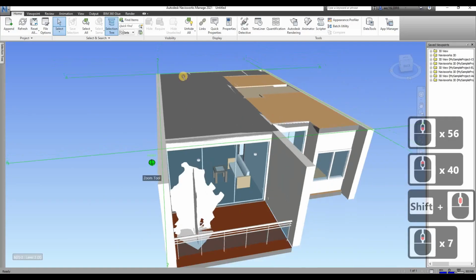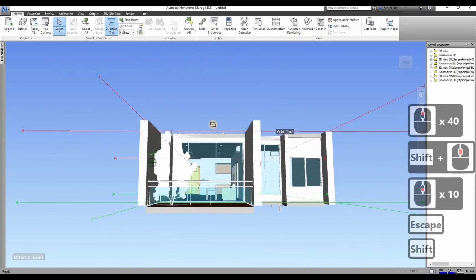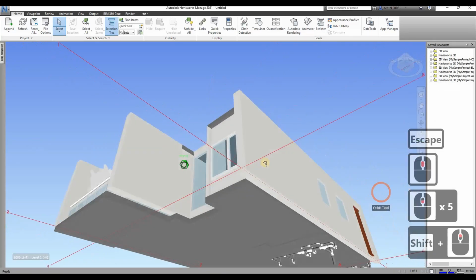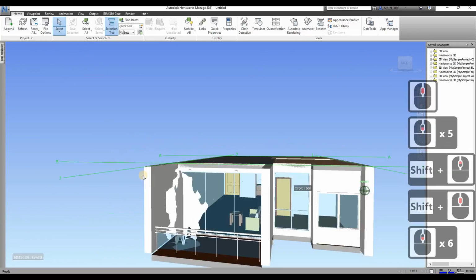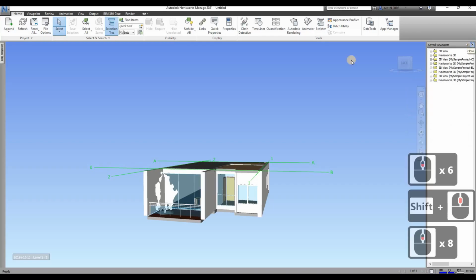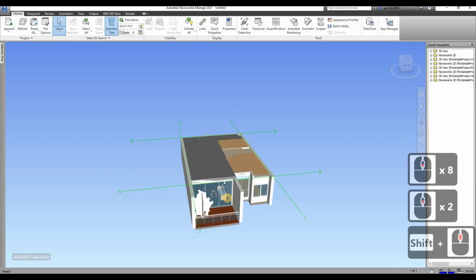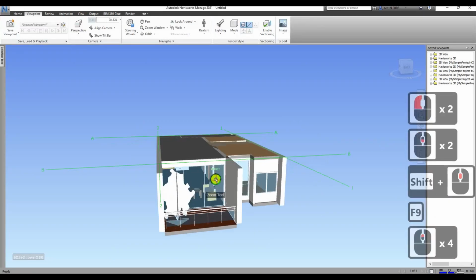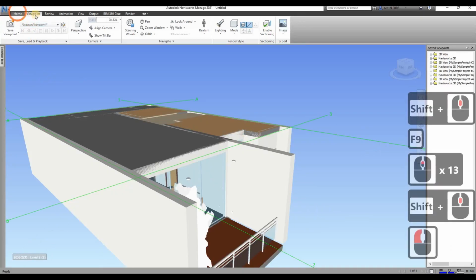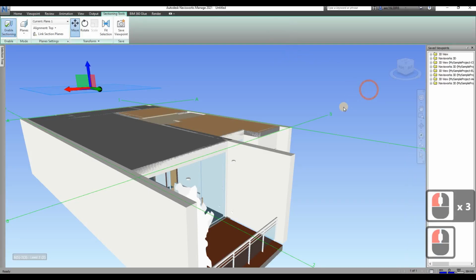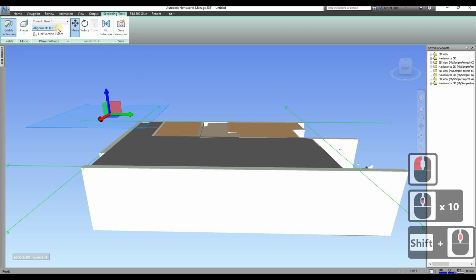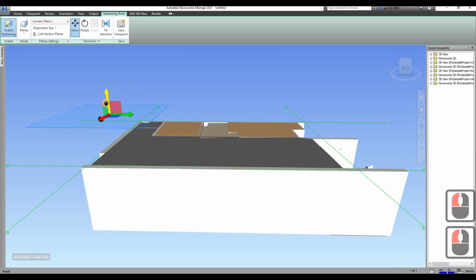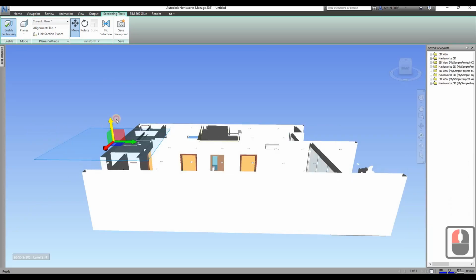Then next, what can we do with Navisworks? First of all, I already mentioned the benefit is you can navigate effectively. Save viewpoints, just leave it. You can navigate through the home and viewpoints here. Then you can enable the sectioning tools. If you want it aligned to the top, you can align to the top, then move your cut sectioning tool below.